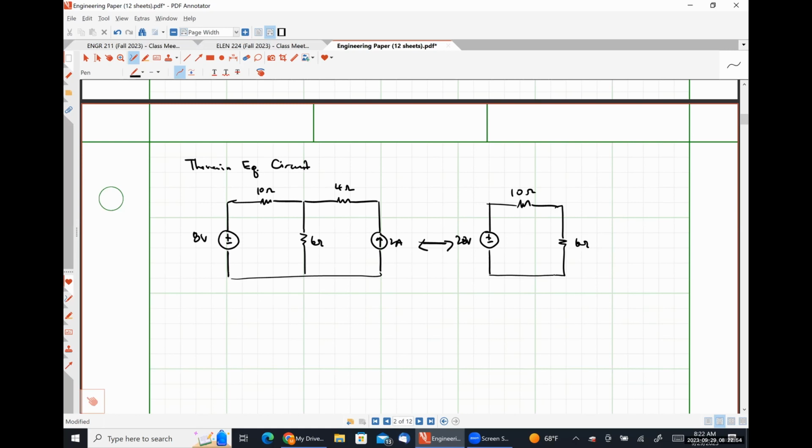And after we cover Norton equivalent circuits here in just a moment, then I'll work a problem where we are just given a set of terminals. So, any questions on the Thevenin equivalent circuit process? Okay. To form the Thevenin equivalent circuit, we need to find the open circuit voltage, which is the same as VTH. And we also need to find the Thevenin resistance, which is just the resistance looking into the terminals of a dead network.